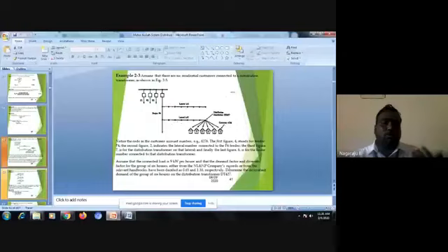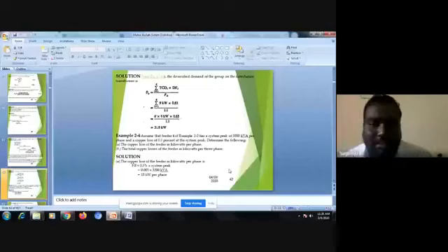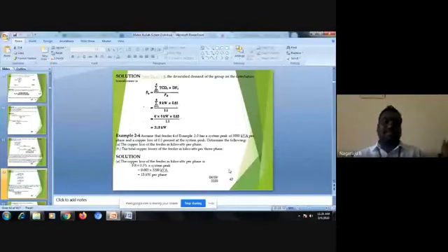To get the diversified demand, we have the formula: total connected load into demand factor divided by diversified factor. You have the diversified factor for the group wise. You have the total connected load. Individual load is having 9 kilowatts. I have 6 into that, so the total connected load I will get is 54. 54 into 0.65 is the demand factor. Diversified factor is 1.1. So diversified demand is nothing but 31.9 kilowatts. This is about the highest one. This is about the first problem.